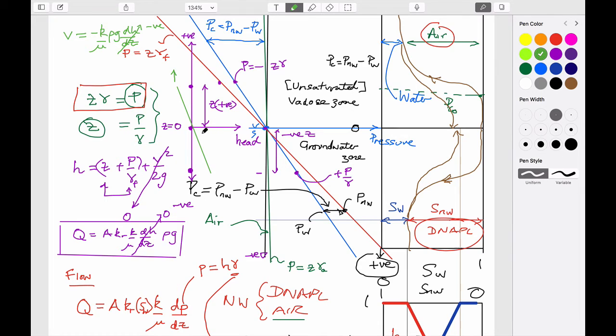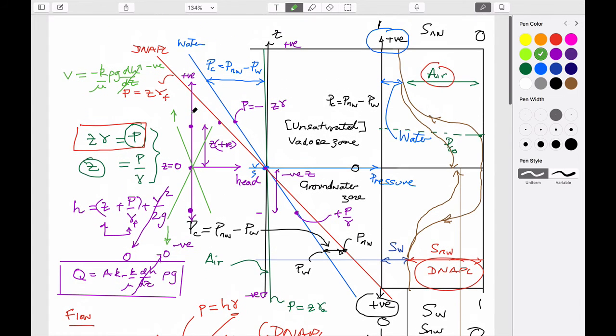If you did the opposite, and you registered a gradient that was going in this direction, then this, by the same token, would mean that flow was occurring downwards. And so if you could measure in situ somehow the magnitude of how head varies with elevation, and you know what the unit weight of the fluid is, then you know by definition what the direction of flow would be, that it wouldn't be in equilibrium. And so it's important in our understanding of these.